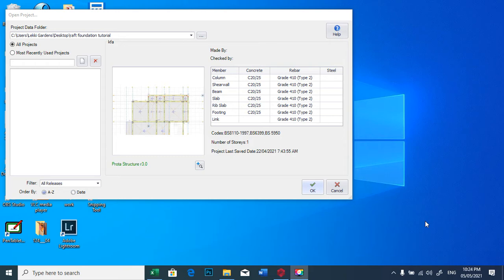Basically two things. One, if your soil capacity is not too good for it to be carried on pad foundation, then you can introduce Raft foundation. Or if you have very high loads coming on the foundation, maybe you are doing a high-rise building, so you will need a Raft foundation to take care of it.